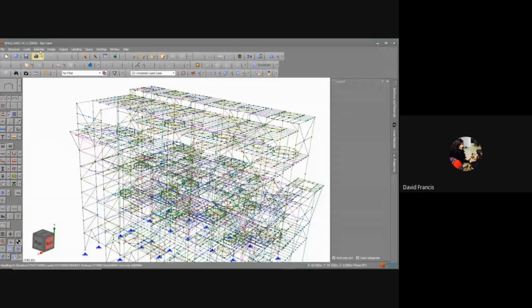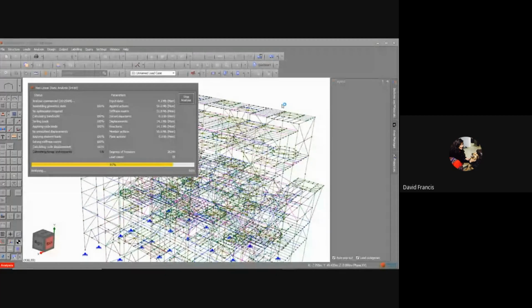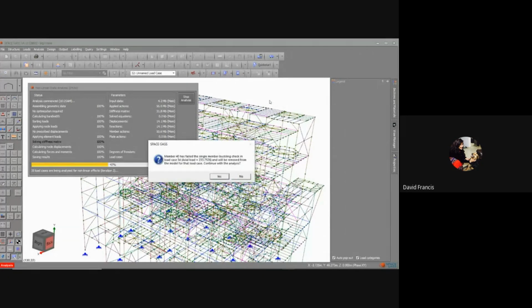So if I come back to the analysis again and rerun it, there are a couple of options. One is I'm going to turn the show messages from single member buckling on. And if I hit the OK, I get these kind of messages.